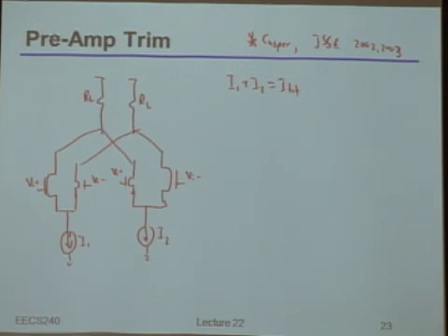Now, having said all of that, advantages, I get to use the bias current, but there's a couple of disadvantages. So what are a couple of the disadvantages you guys might see from this? Okay, you said you're not sure about the linearity of the DAC. Turns out it's actually pretty darn good. Because in some senses you can think of it as you're just linearly interpolating between the individual offsets created by each of these two guys. You're right, you have to do a slightly more detailed analysis, but it actually turns out to be pretty darn good.